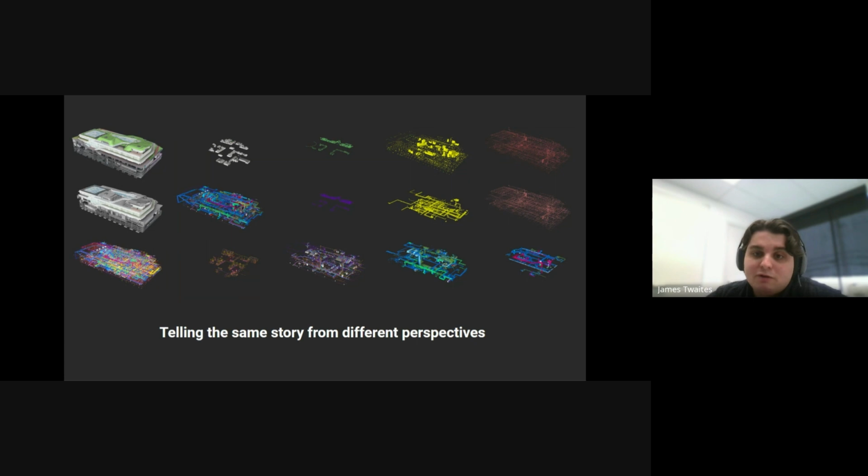is that the foremost expert on every system at any given time is the one responsible for that model. And typically to achieve this, that means authorship over some elements gets transferred through the project. For example, in the top right there is the fire protection model from the fire protection consultant, and then right below that is the installation model from the fire protection contractor. So once the design is complete and represented by the consultant, the contractor can take over and fine tune for installability. They can account for any offsets that they need to avoid other systems. They can optimize the arrangement of their fittings and do that kind of thing.